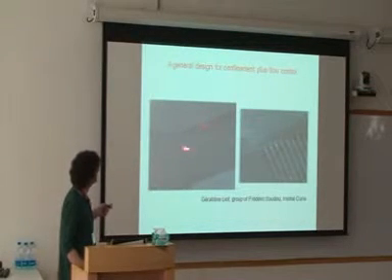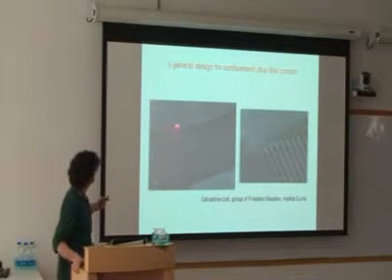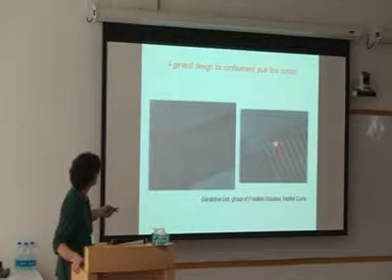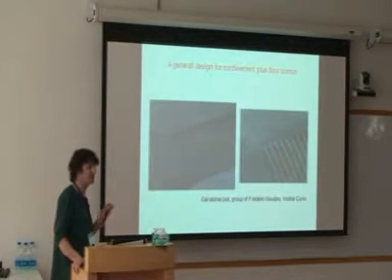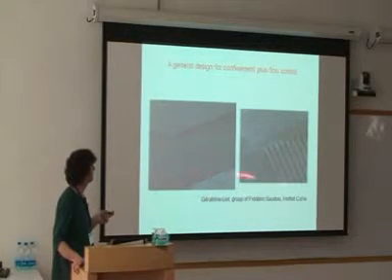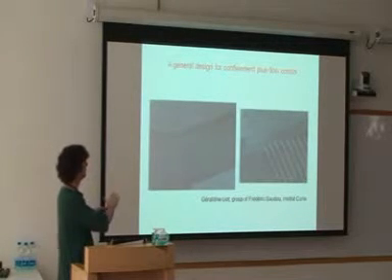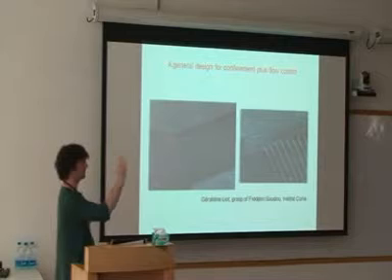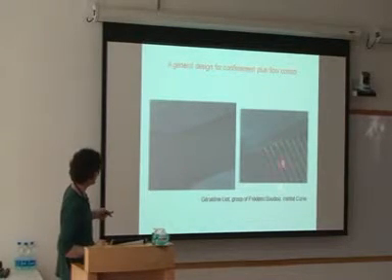This is what it looks like if you look at the mold that you would use for these channels. You have the big channels and the small channels. I also give that example because in terms of fabrication, it is very easy to make. It looks like it's tricky, but it's very easy. What you do is you have simply a mask with lines, and you print these lines on a thin layer of photoresist, and that will give you your small lines.